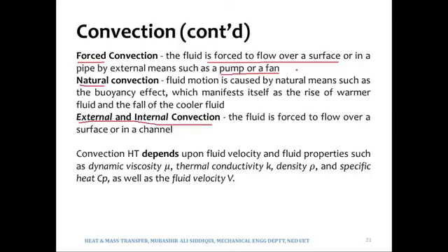So the bulk fluid motion is increasing with the increase in velocity, which will in fact increase the convection heat transfer rate. So the forced convection would result in higher heat transfer rates as compared to natural convection.